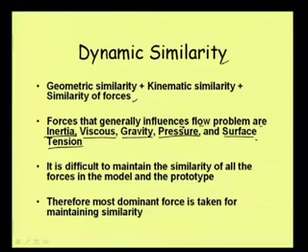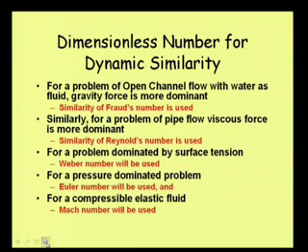So, the most dominant force is taken for maintaining dynamic similarity, basically. Let us see for what sort of problem, what sort of similarity we need to maintain. Say, for a problem of open channel flow with water as fluid. Why are we saying water as fluid? If we talk about viscous fluid, then this may not be valid. But for an open channel flow with water as fluid, the gravity force is more dominating.